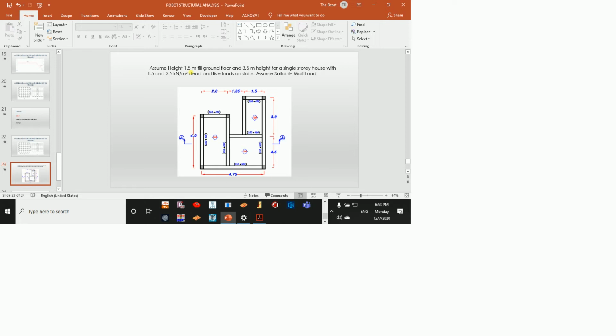But normally consultancies have a fixed value for finishes. Some of them use 1.5, some of them use 1. That depends on the finishing material. For example, if I'm using granite, then it's going to be different than using regular tiles. But anyhow, I'll show you what the code is where you can get these values.